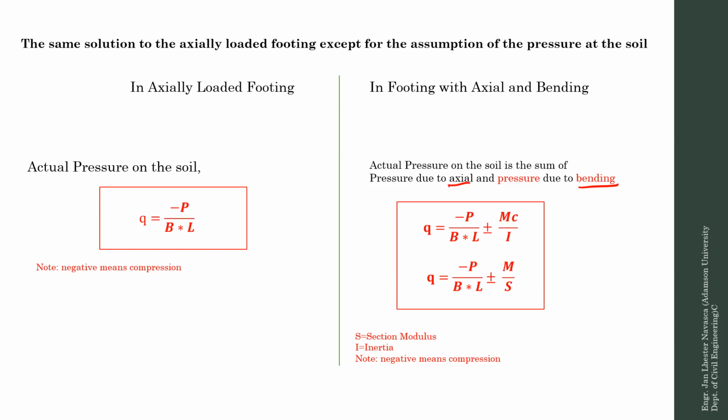Flexural stress or bending stress. If you recall from strength of materials, the formula for the flexural stress is basically MC over I. Moment, central distance, inertia. That is the flexural stress.